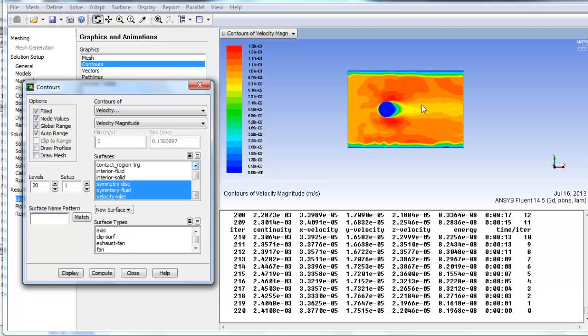So we had quite a rough mesh around here, so maybe that's where you can see it's not. It should really be symmetric about the horizontal line there. The reason I didn't do a symmetry plane there is that once we spin the disk we would lose that. So I did the full domain, but really it should be symmetric about there. And the fact it's not suggests that either the Reynolds number is too high, but I don't think it is. It's about 10 to the 4 for laminar flow, or that the mesh is not good enough. And I think the mesh is just not good enough.